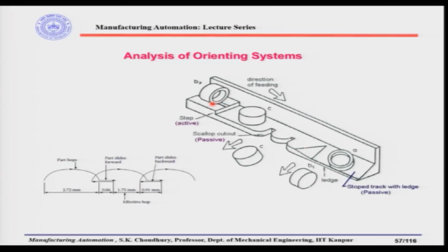Normally a soft aluminum floor is arranged, and the parts are thrown at random onto that floor from a certain distance, and we observe how those parts rest on the soft aluminum floor. For example, suppose our desired orientation is this, that is, the heavier side down. The parts which are coming can have 4 orientations, as I discussed earlier.